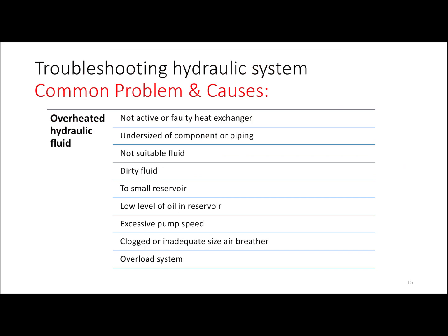Okay, meaning the filter is already faulty, or else the reservoir is too small, so there is no temperature exchange between the distributed oil and the oil in the tank. Or else it is because of a low level of oil in the reservoir. Then, because of excessive pump speed, friction increases, temperature increases, and the hydraulic fluid also heats up by this kind of reaction.